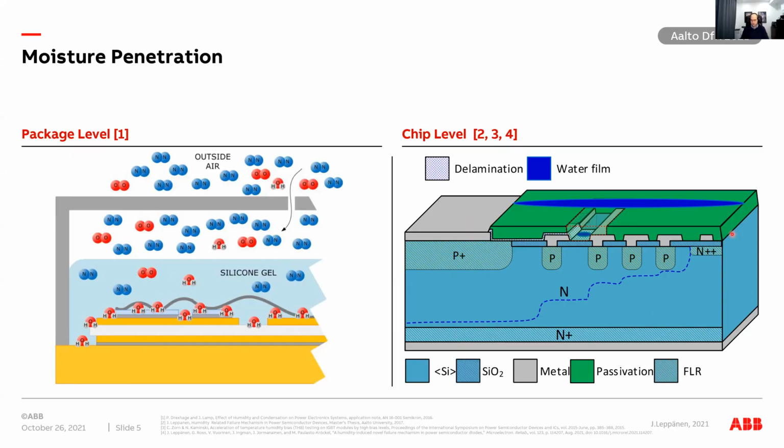So eventually, if there would be this high voltage here, you can calculate what's the electric field. It's really high, and there could be a breakthrough through the edge. And especially because the bottom side of the chip is typically solder, and there can be solder splashes on the edge of the chip here. So definitely this can cause a breakthrough. So that's why we need this kind of a terminating structure, and it has to work there.